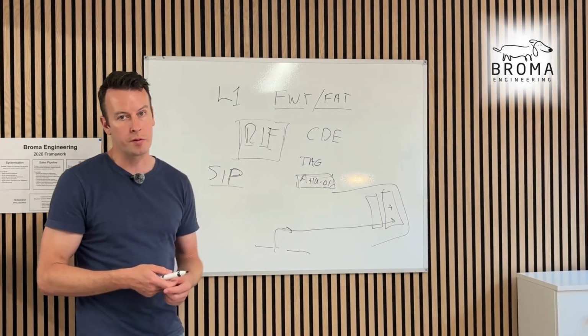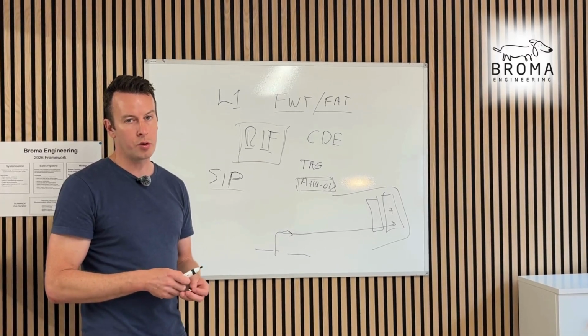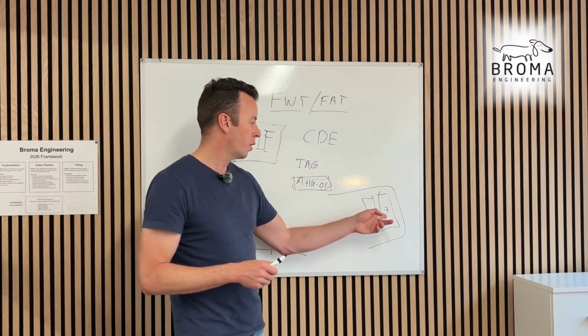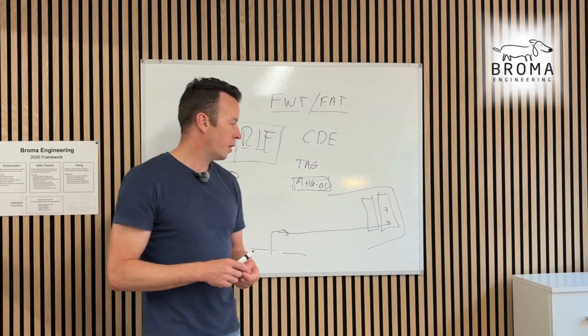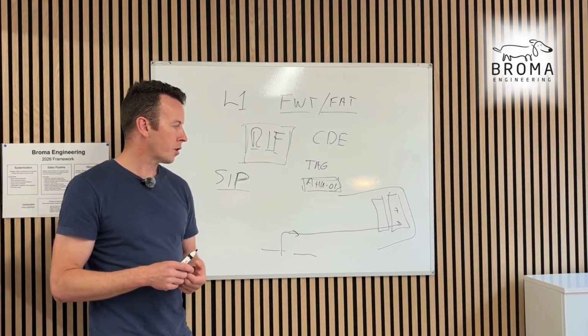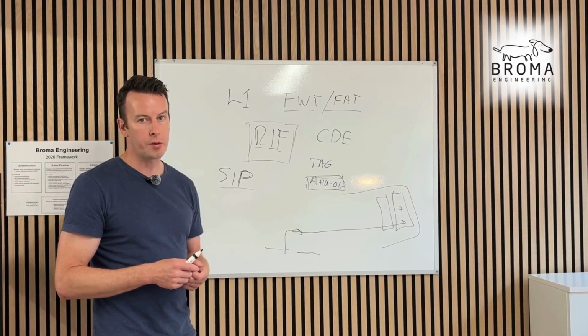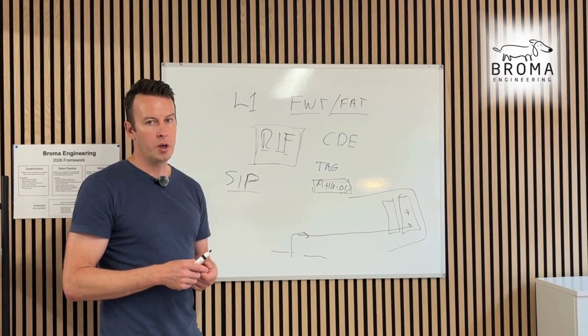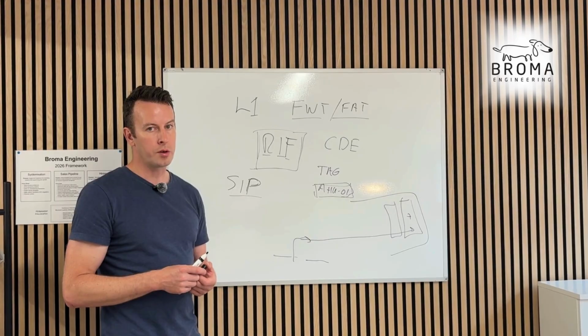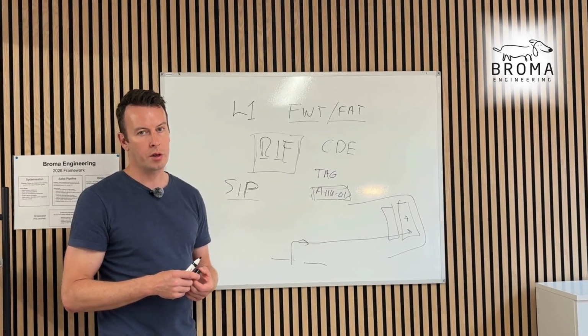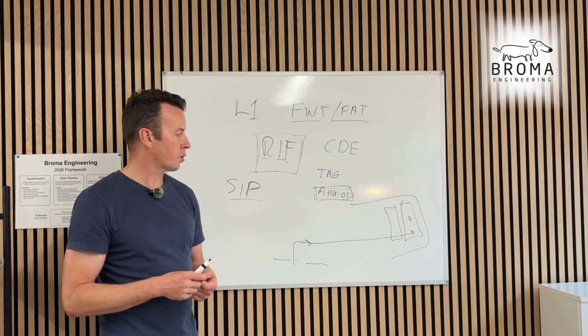It might be stored outside for a few weeks. Then you unwrap it, it's covered in mold. And some of these materials for the AHU, they're not designed to be in those conditions, so they can degrade quite quickly if there's not air flowing through them. So really make sure that all those things are covered with the vendor, and they have all the precautions taken